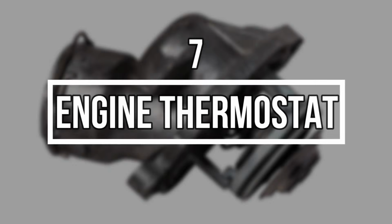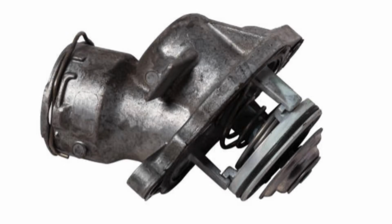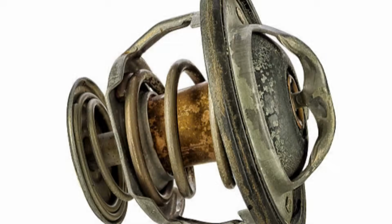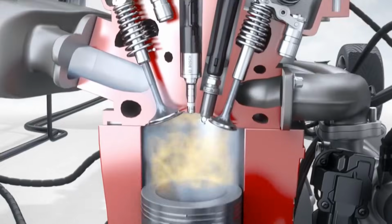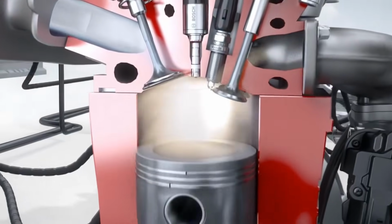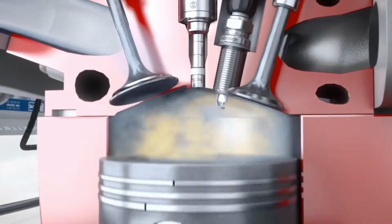7. Engine thermostat. The engine thermostat is responsible for keeping the engine at normal operating temperature most of the time. If the thermostat becomes stuck in the open position, the engine will remain cold, especially at highway speeds and during extended driving. This causes the ECU to continuously enrich the fuel mixture in an attempt to warm the engine, resulting in increased fuel consumption.